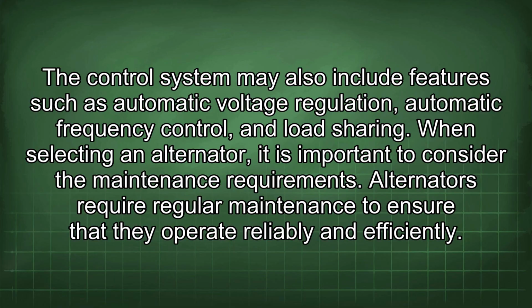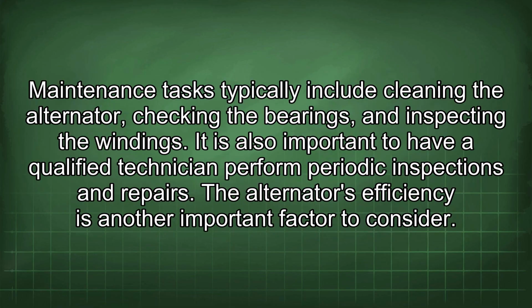When selecting an alternator, it is important to consider the maintenance requirements. Alternators require regular maintenance to ensure that they operate reliably and efficiently. Maintenance tasks typically include cleaning the alternator, checking the bearings, and inspecting the windings. It is also important to have a qualified technician perform periodic inspections and repairs.